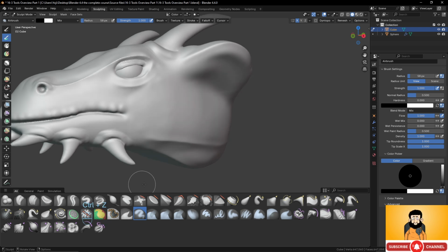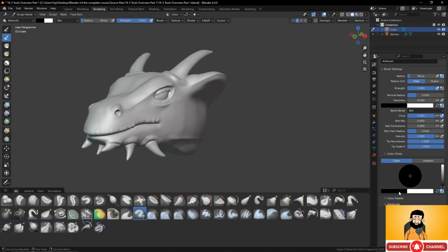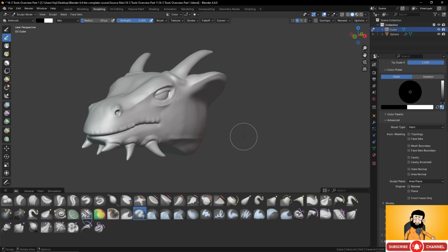You can really paint your object like you want, exactly like in texture paint, but it will create a kind of specific painting for the sculpt mode. So just for showing your object it can be very good. You can add some textures. It's exactly the same options that you have in the texture paint, but you will not paint on textures. You will paint on vertices, so it will be different.